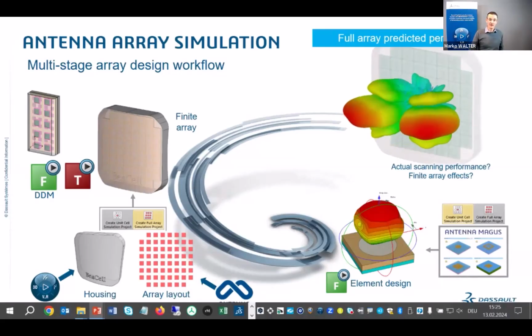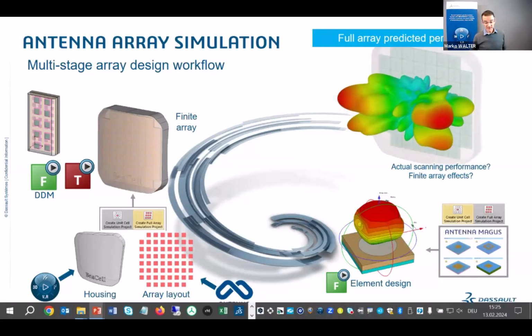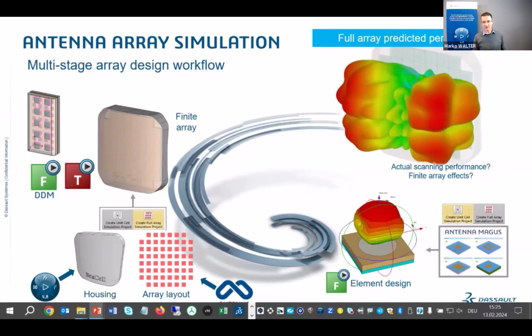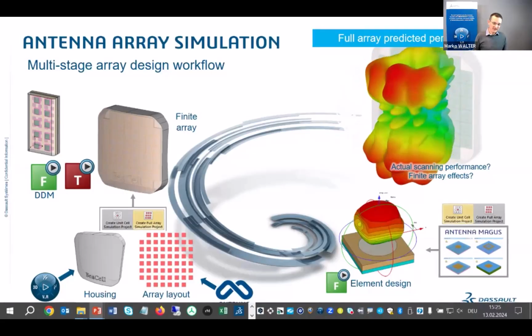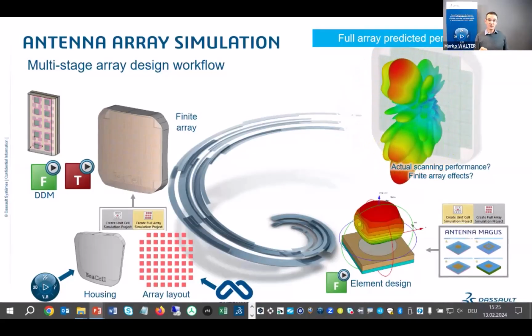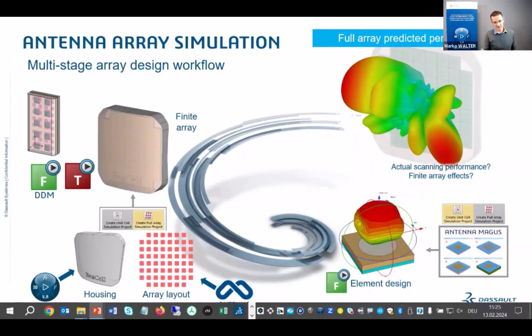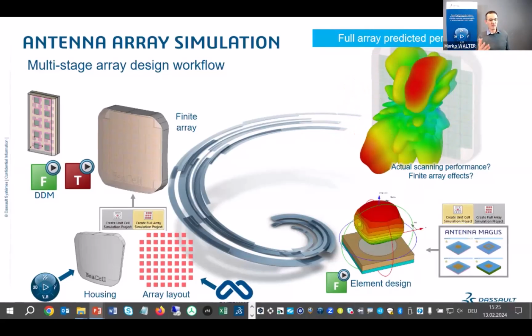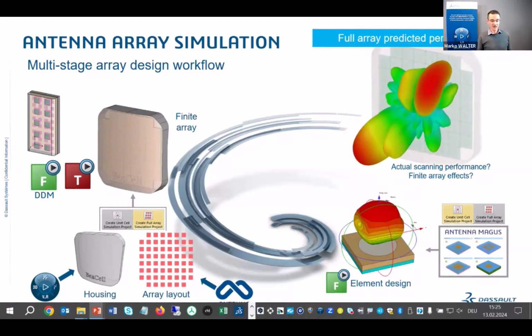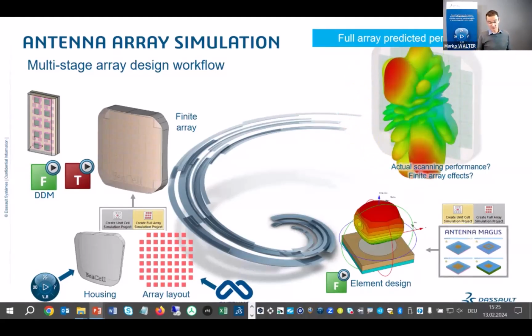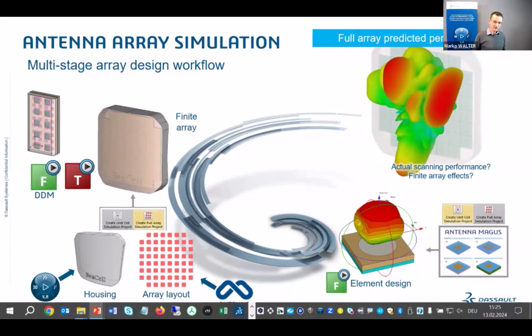Should mention here, again, a little bit about the solvers that are being used. At the element design level, we're using the frequency domain solver with unit cell boundary conditions. At the finite array level, we're also often these days using the frequency domain solver, but in its domain decomposition method form, so the DDM frequency domain solver. Or we could use a time domain approach as well in certain cases.